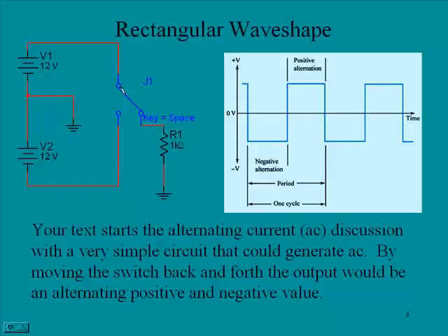Now, when we pull the switch down and connect it to this point here, notice now we're connected to the negative side of a battery, and so current is going to flow again through here. It's going to come through here, go across the switch because it's pulled down now, and go down the resistor. It's a little bit confusing. It looks like a figure 8, but this would be the path for current. The difference here is that the current is flowing down through the resistor rather than up. And in this particular configuration, that is where we're going to be generating the negative part of this square wave.